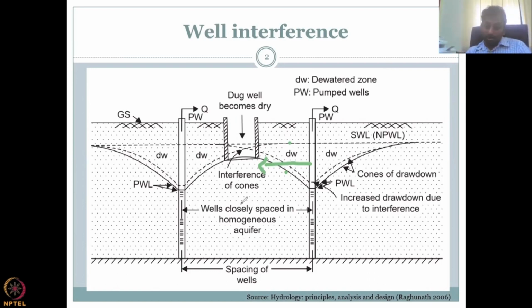If the medium is very permeable, it's easy for water to move, then you will be pulling a lot of water. Otherwise, if it is cracks and hydrologic fractures, then you won't have much connection, so your pumping may not be influenced. This is why you should keep a monitoring well that captures all these dynamics, rather than keeping one here, not even in the full aquifer width, saying that my water level is okay because it is not influenced by this interference.